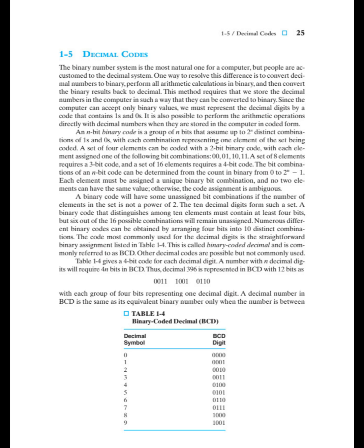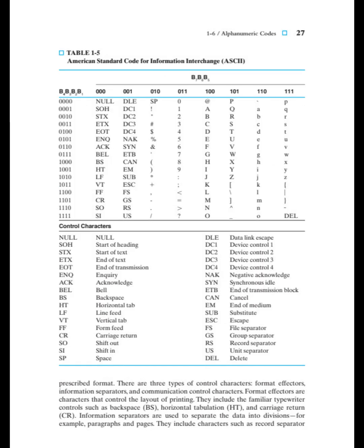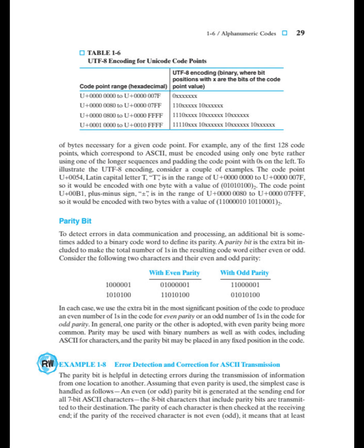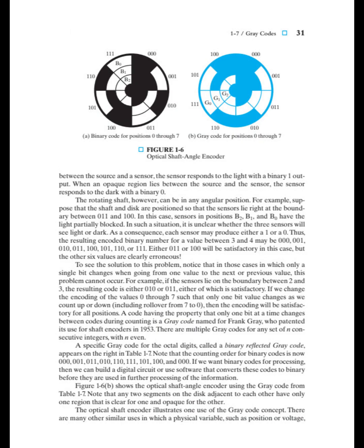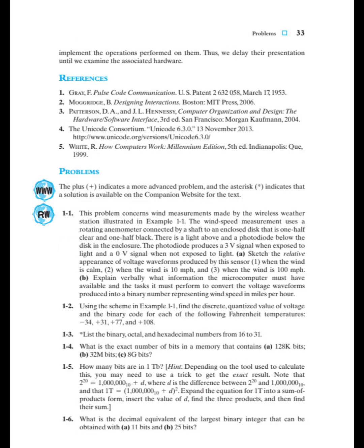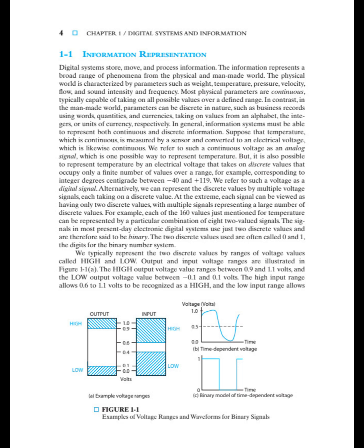And then this digital temperature reading gets transmitted wirelessly to the indoor base station. Okay. What happens there? Well, the base station gets this digital data. Its microcontroller might do some processing, maybe calibrate the reading or format it nicely. Now, if the base station has an old-style analog meter with a needle, it needs to go back the other way. Convert the digital number back into an analog voltage. Using a DA converter. Exactly, a digital to analog converter. This produces voltage levels that try to approximate the original analog signal. Cool. Often you'll have extra circuitry to smooth those voltage levels, make it more continuous for the meter. So it goes analog, digital, then potentially back to analog? It's a full circle. Wow.